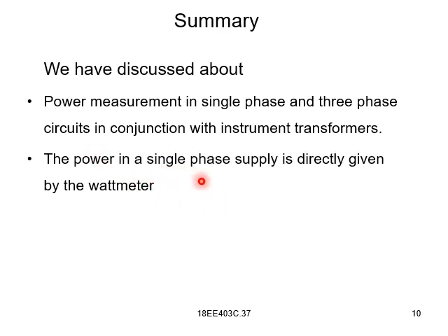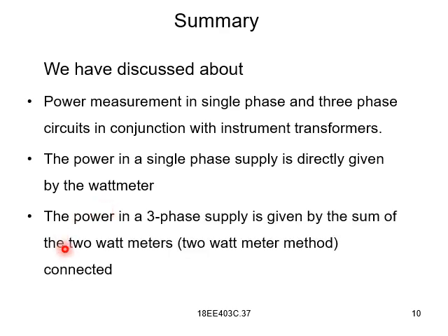The power in a single phase supply is directly given by the wattmeter. The power in a three phase supply is given by the sum of two wattmeters, that is, the two wattmeter method connected. So these are the things which we have discussed. I hope you have got some idea.